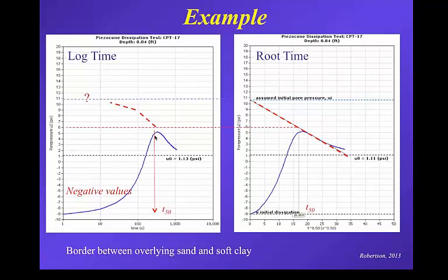It's hard to imagine that maybe it started at a very high positive number and then eventually ended up at a negative value. Of course, there is always the chance that the zero drift on the pressure sensor drifted a little bit off, and the accuracy of the pore pressure may not be so good. And certainly when you're measuring pore pressures close to zero, then you're going to lose some level of accuracy.